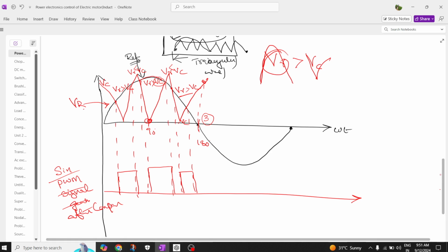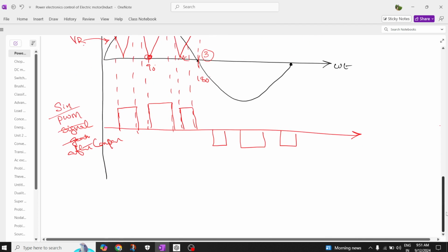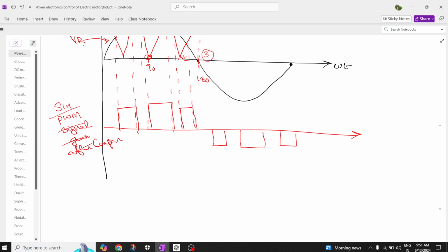Sinusoidal is greater, the control, I mean the triangular wave, is lesser. Here sinusoidal is greater, where the triangular waveform is of lower magnitude. That's why here we are going to have the output. So I can draw for the remaining, but when you consider positive or negative also, you'll get the same. So you'll get like this. Okay. So I don't want to elaborate it more, because I got the required output. So this is a sinusoidal pulse width signal generated from the comparator.